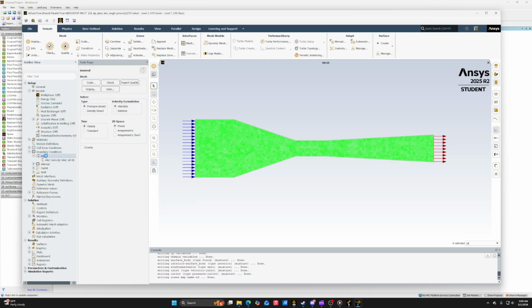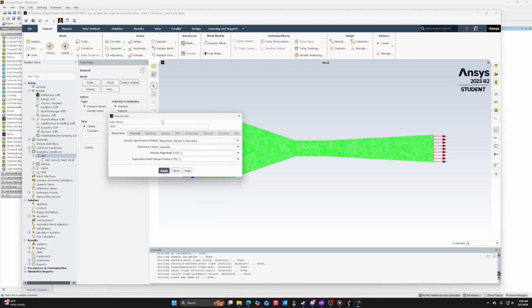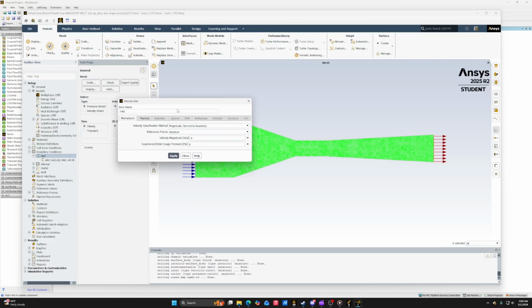We're gonna press inlet, and this is where we're gonna use the velocity equation that was given in the project. Since I'm doing 20 hertz, my velocity in the test section was 4.6062. I used that to find the velocity in the settling chamber. I used V1 A1 equals V2 A2. And that I got the settling chamber velocity to be 1.25626. Perfect. And this was for 20 hertz.